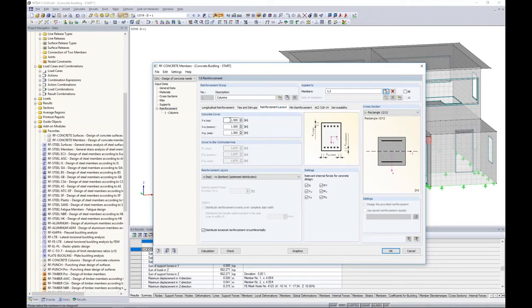The reinforcement layout. The first thing to set here is the concrete cover. The ACI standard refers to Table 26.13.1 for concrete designation, and for number 5s or smaller that are exposed to weather, the code tells us that 1.5 inches is adequate. So assuming we're using number 5s here, we'll just keep this as the default of 1.5 inches. If the program came up with number 6s for my reinforcement, maybe I'd want to go back and adjust this to something more like 2 inches.